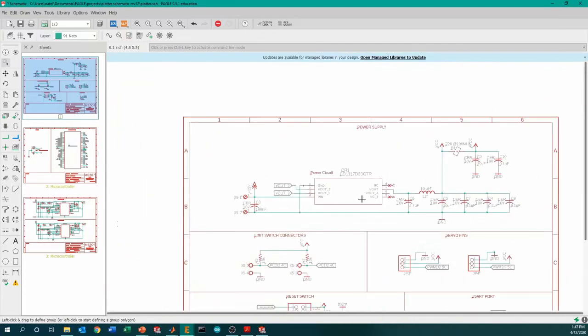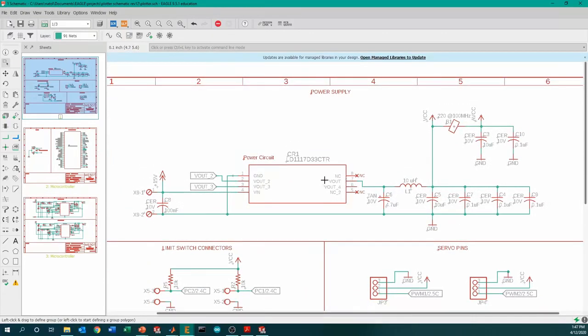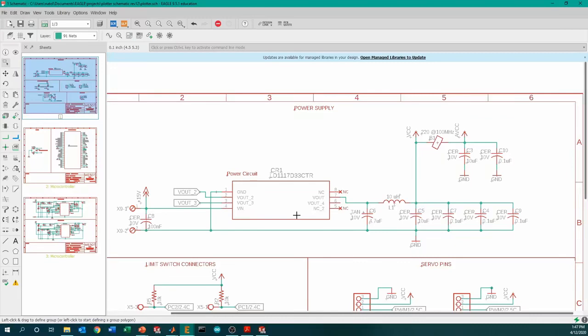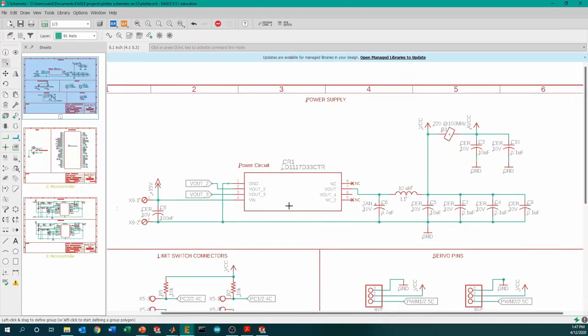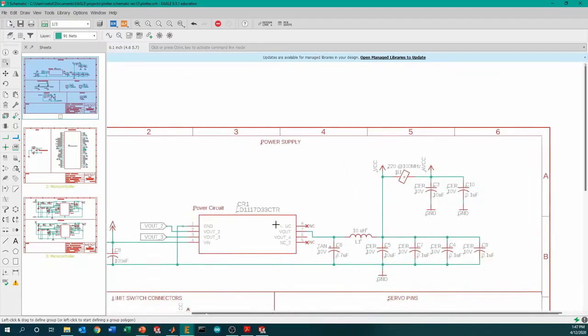So, relatively simple setup. We basically have our power supply, which gives power from the 24 volts, which had been already stepped down to 15, down into the 3.3 volts that the microcontroller runs at. We have our analog and digital portions of the controller set up, so our AVCC here, and its own decoupling capacitors located close to the appropriate pins, separated by our bead, and our inductor down here, and of course our individual decoupling capacitors on our VCC side.